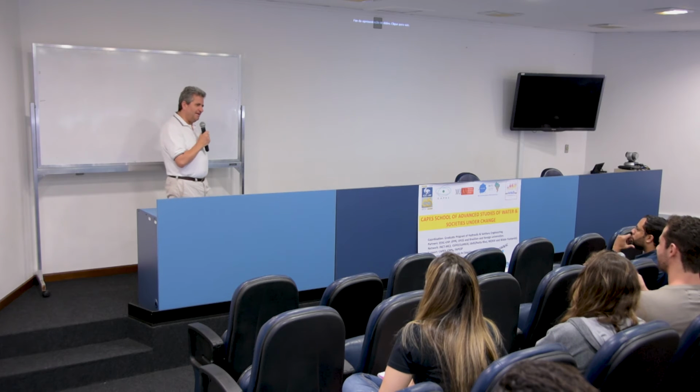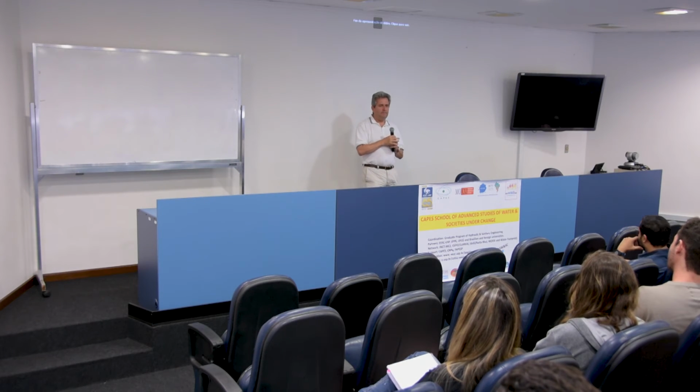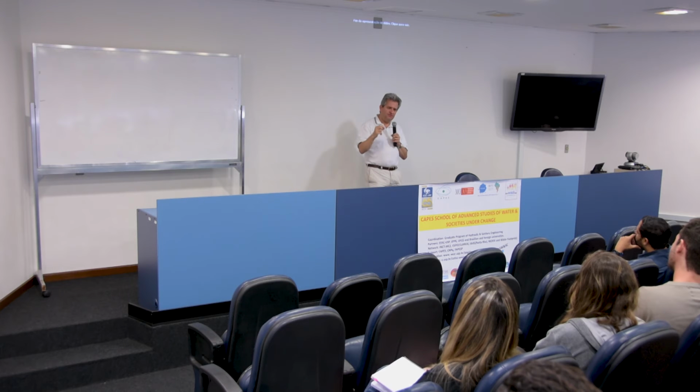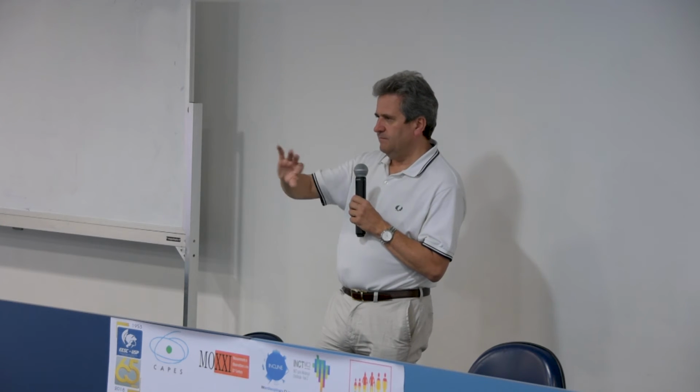Yeah, you speak like a man of experience, actually. As you know, there is such a process. It's called dissolved air flotation. So what we do is, instead of settling the particles, we introduce a stream of very tiny air bubbles, which obviously float up. And the air bubbles have the property that they will stick to the hydrophobic particles, and therefore the hydrophobic particles float up, and they can simply be scraped off.